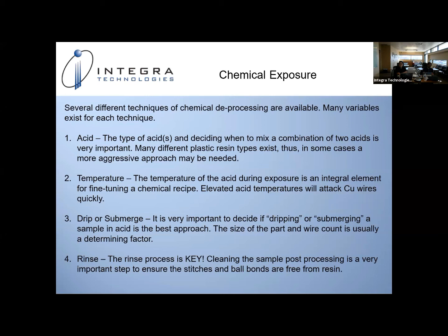the bond pull and the likes of it. In the case of gold wire, there's a lot of forgiveness because you can over etch it and still take care of all the molding compound. In the case of copper bond wire, the forgiveness is very little.